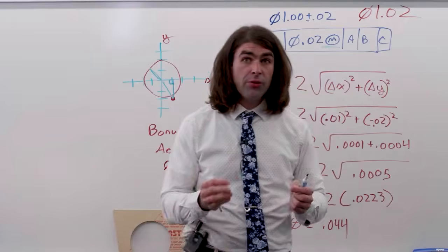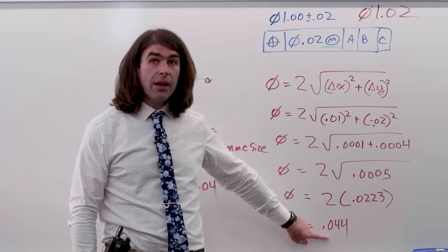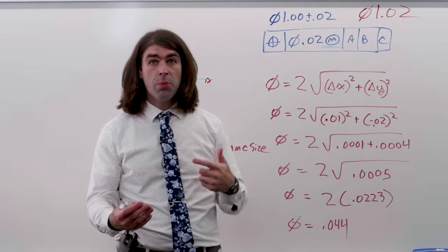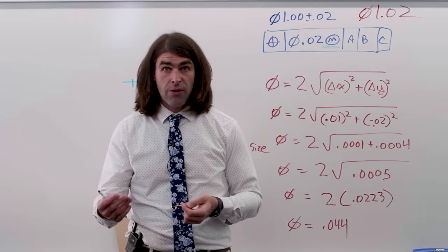That's how much tolerance we have. We can compare it to our calculation over here. Because of the MMC symbol and that the hole came in large, this part would be acceptable at this point. Now, you have to go do this for every hole.